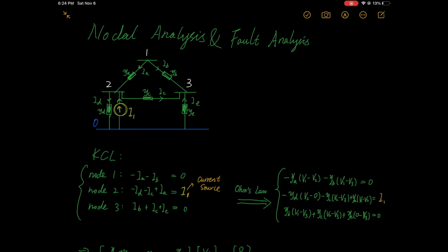Transmission networks consist of numerous nodes and branches. The systematic way to study the network behavior is nodal analysis. When it comes to voltage, it is the difference that matters. So we choose a reference node, and then the number of variables is equal to the number of equations. The KCL equation at the reference node is redundant because it's a linear combination of equations at other nodes.